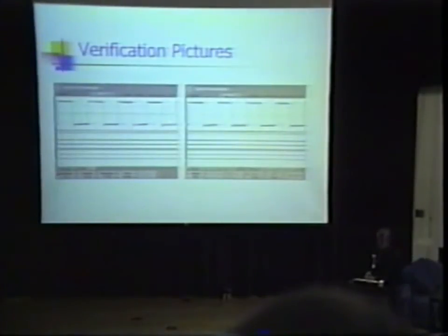These are a couple pictures from the oscilloscope. The top signal is the square wave. The bottom 8 signals are the contents of the seconds. The left picture shows the frequency running at about 8.2 kilohertz, which is very good. And the right shows the seconds being counted in BCD. It shows 47.